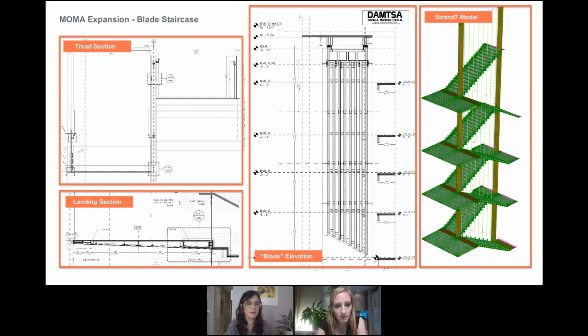But the interesting thing that you have to consider is the response on the landing of somebody walking up or down the stairs. That could potentially be the controlling thing. So you need to consider somebody walking on the stair, how that's perceived on the landing, as well as walking on the landing, how that's perceived by the landing. It's more of a pattern loading, isn't it? Yeah. One's impact on the other, rather than necessarily in isolation on its own. Yeah. Well, I suppose that's a good point, and a good place to wrap things up.